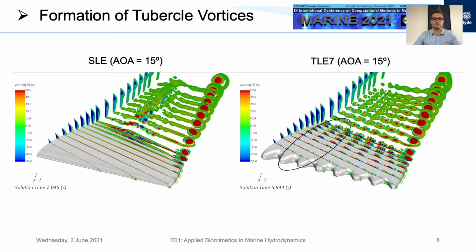It can be seen how the streamwise counter-rotating vorticity is initially generated at the leading edge and builds up over the surface. It significantly increases in strength around the stall cells. The tubercle vortex pairs have a compartmentalizing effect over the suction side surface, limiting spanwise flow. Still, the general spanwise flow component causes the negative tubercle vortices to be annihilated. But the positive vortices persist within the downstream wake and break up the trailing edge vortex sheet and withdraw energy from the tip vortex.